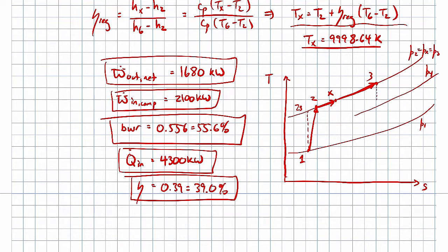Here's what it would look like if it was isentropic. That would be 4s. But it's not isentropic, so we go to state 4 here. Then we go through the reheat combustor. That's a constant pressure process, and that gets us up to state 5. The temperature at state 5 and state 3 we were told were the same. Those were leading into the turbine. So state 5 will be right there. We go through the reheat combustor upwards. So P5 is equal to P4.